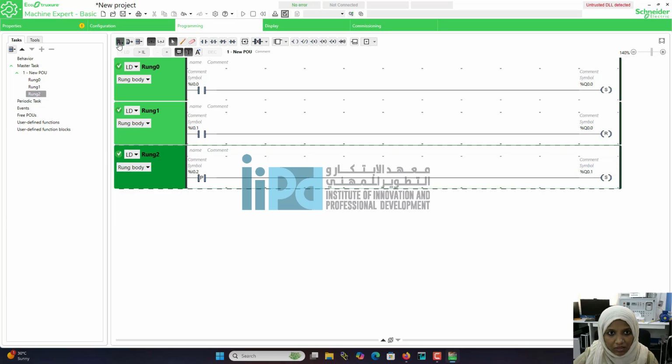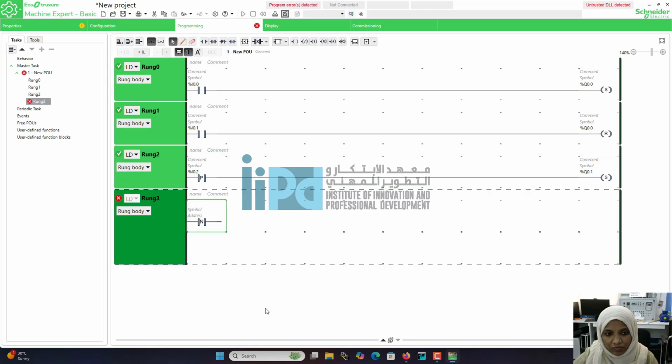Again, let's see the negative trigger. Negative trigger means first your switch is on. So you turn on the switch, then everything is on. Now when you turn off the switch, there is a change from on to off, or 1 to 0. If you want to detect that change, for example something was working in your industry and all of a sudden something turns off, and during that time you want to detect it, in that case you can go for negative triggers. If you connect that input to the negative trigger, it will generate a pulse and your output will be on. That can be given to a reset condition or a set condition. It's up to you. With this pulse you want to set something, or reset something. Anything can be done.